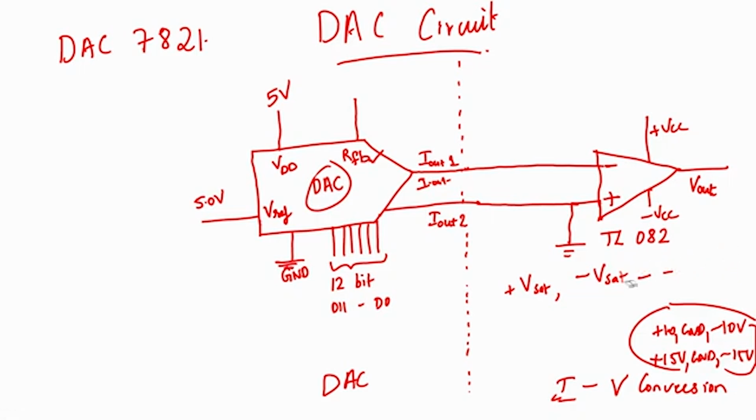So, we should have a negative feedback so that our gain is controllable and we get measurable output values that change with the change in the bit sequence. Otherwise, whatever small input we give, because of the infinite gain of an open loop op amp, we will always get the saturation voltage as the output. That is why feedback is provided. These are basic op amp concepts which we will reiterate again and again, so that they become very solid and you can use them to build intelligent systems. Going further, we will see other applications where we can build systems such as these.